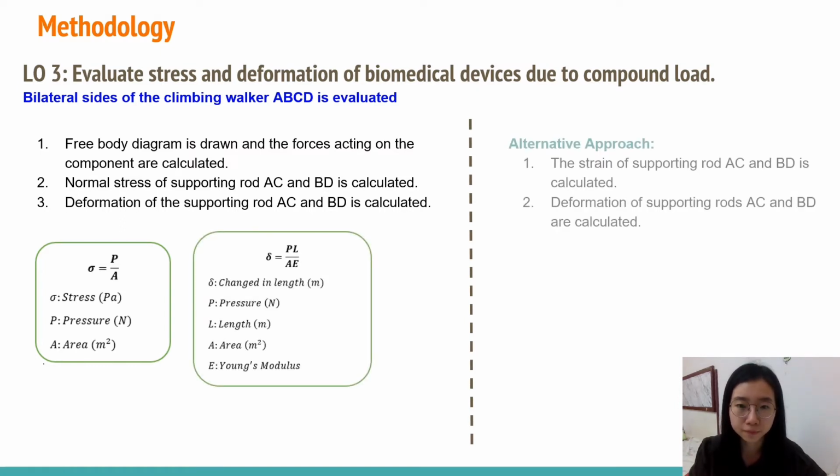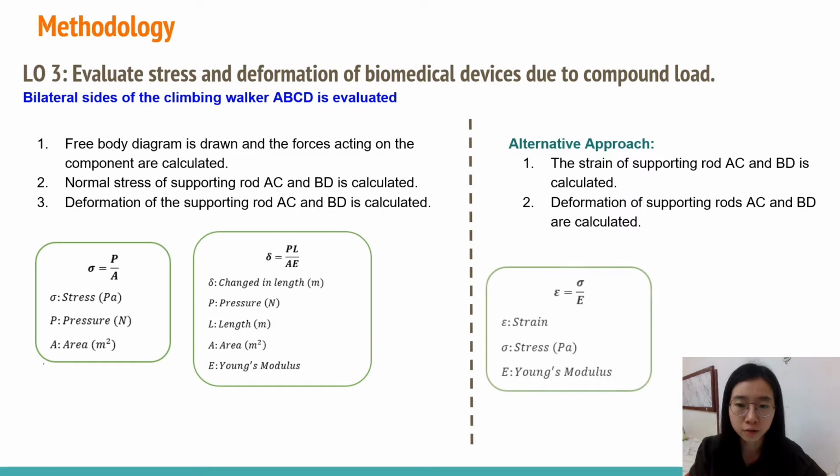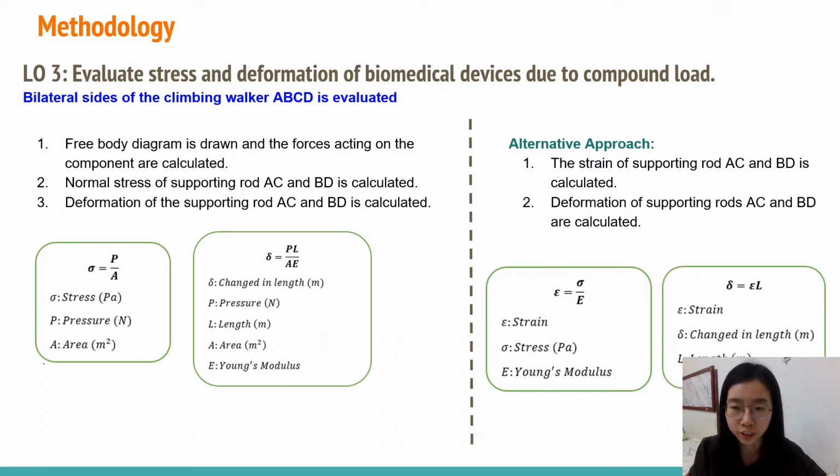There is an alternative approach to get the deformation. The strain is calculated by using the formula strain equals stress over Young's modulus, and then the deformation can be obtained by using the formula strain equals change in length divided by original length.